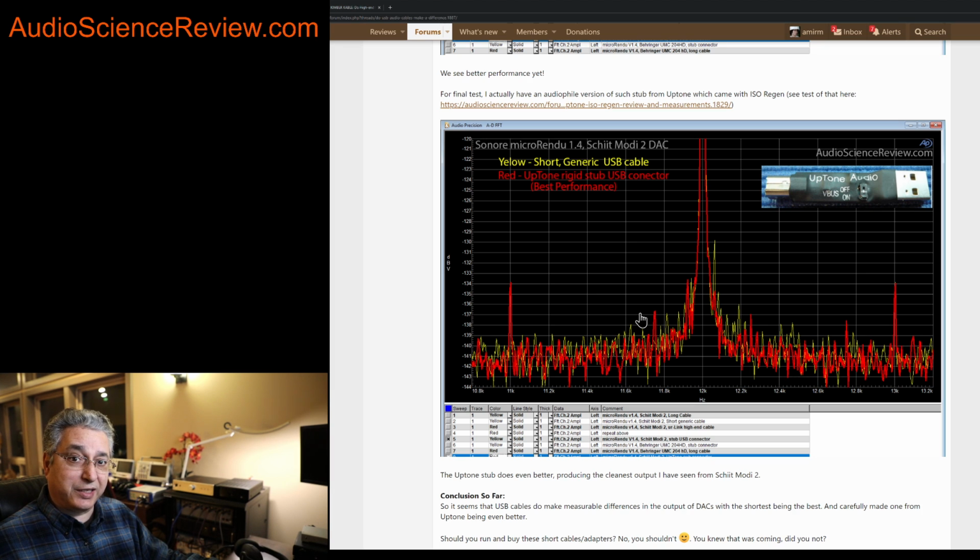So be careful in saying digital is digital, bits are bits, in these arguments, because that argument does not hold. Because USB is carrying data, we are able to extract data reliably in these short lengths. But it's also got power and ground, and that power and ground is used in a DAC. If a DAC doesn't properly filter that 5 volts before it uses it, or it's not designed well, it can get into ground loops with the computer, which happens to always have a noisy ground, and you can impact the measurable analog output of the DAC.